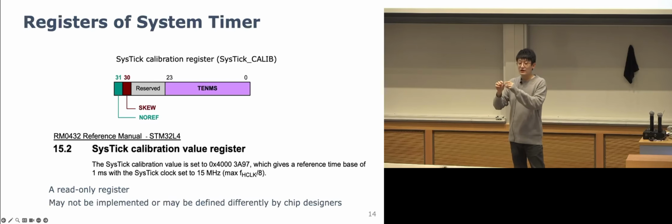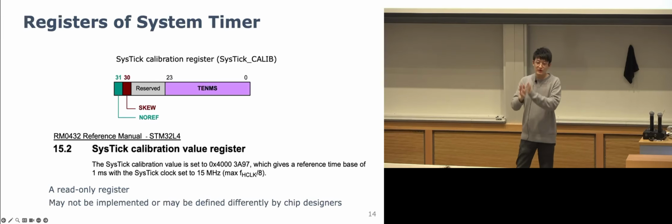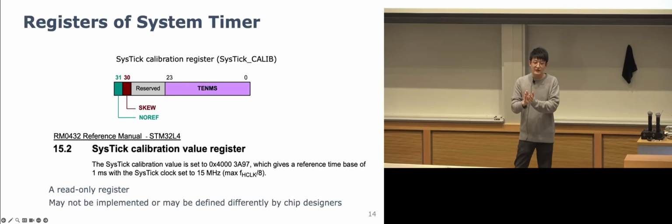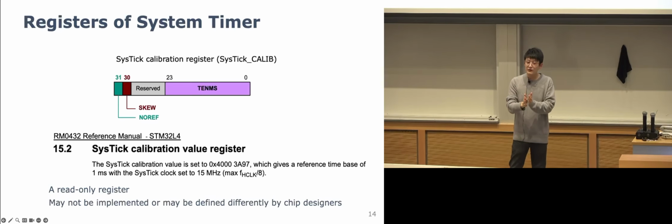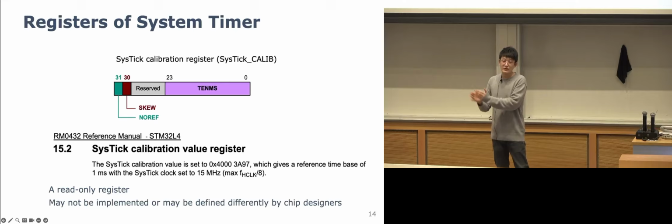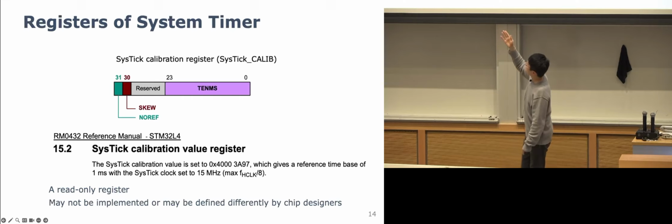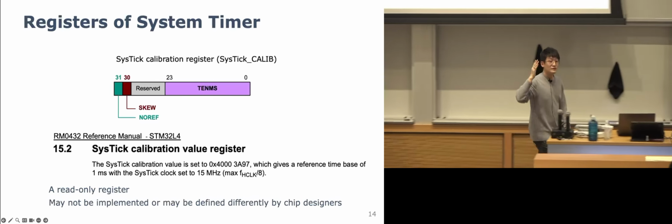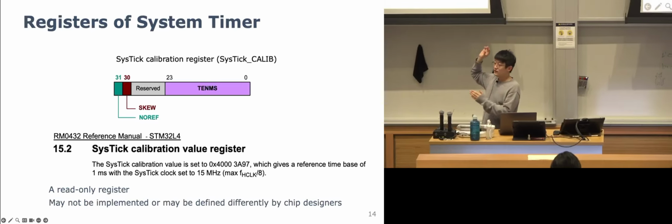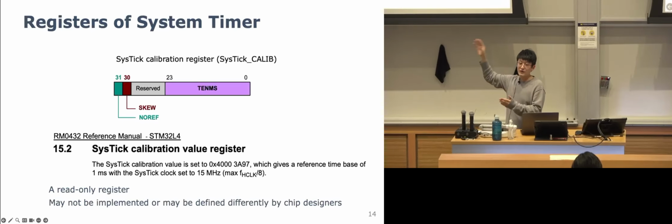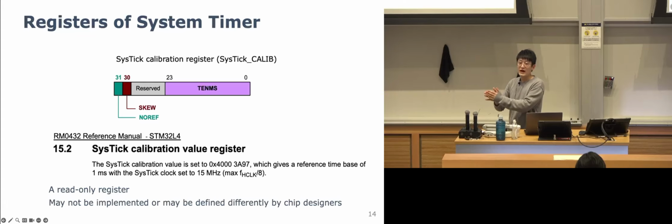So it's not, so to speak, an integer value of a millisecond or second, then that no-reference flag will go up, so that you know that this is its own SysTick counting, but we don't necessarily take this as the real world time to use in the system, but it will still count nevertheless.